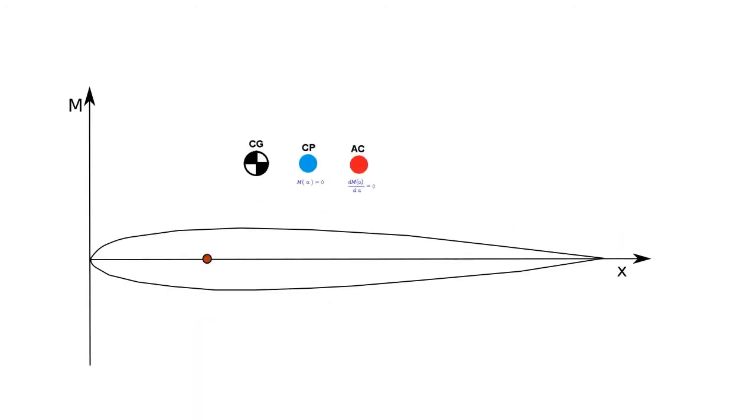And the moment is presented here with this axis. So here is the moment coordinates. So here is the position where the moment is equal to 0. And the moment can be computed at any point in this 3D space. And if you know the moment in one position, we can compute the moment in any other position using the property of the moment function. Because this function is additive, we can sum those moments, so we can derive an equation to compute the moment in any other position.